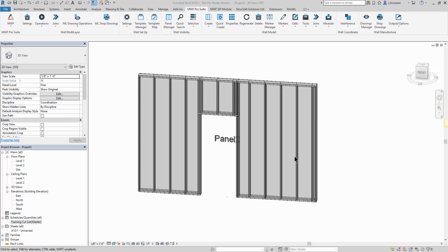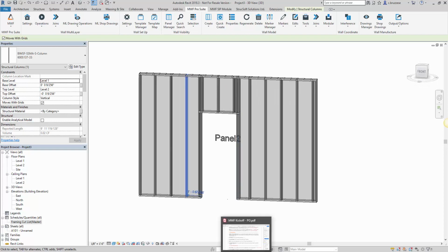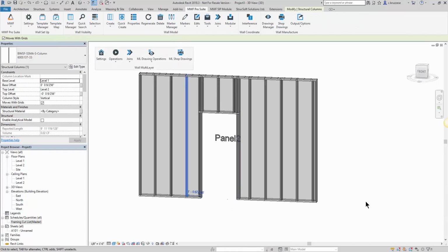We're going to be covering something a bit different this week. We're going to mainly be focusing on how to add a schedule label to our multi-layer shop drawings. The schedule label basically enables you to quantify everything that's identical and give it one common label. And then we'll also be able to reflect that back in the Revit schedule.